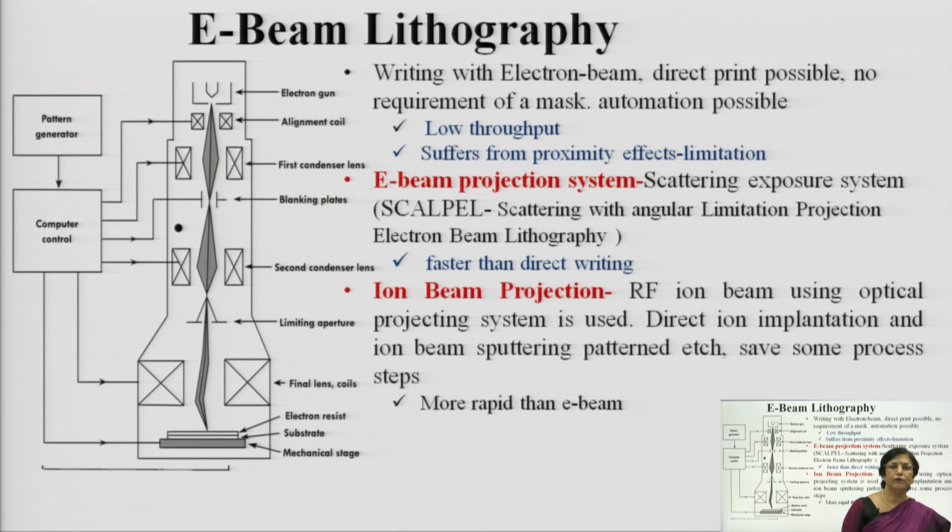In positive photoresist, where resins are used, the bonds get broken, and once the pattern gets exposed to light, that area becomes soluble in the solvent. When you develop the wafer, the portion where the bonds were weakened will get dissolved automatically.